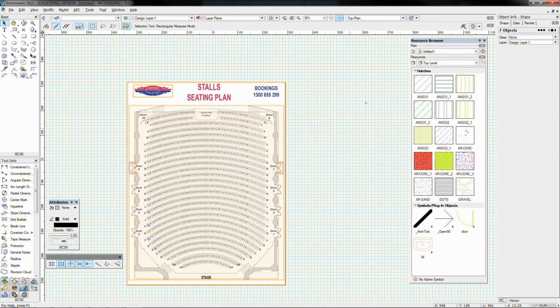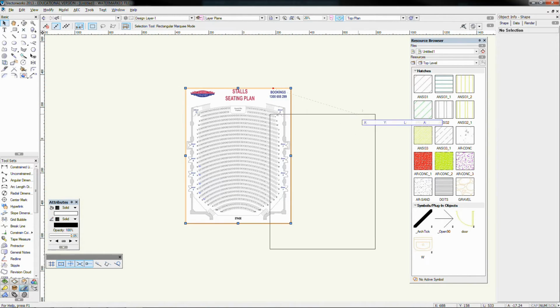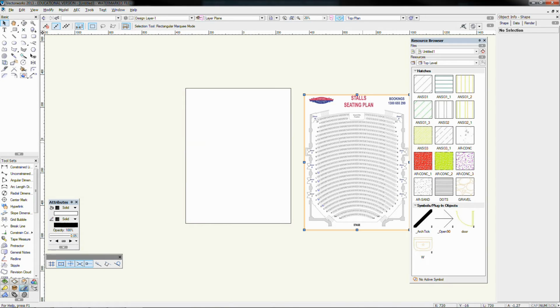And it'll probably spit out a couple of objects. There we go, 7 objects up in the top right-hand corner. Now at a guess, the smart cookie, whoever's drawn this, has broken it up into some walls, probably some seats, and maybe a few doors and some background images. So the first thing you'll be left with, if I just drag these components out individually, is the original PDF. It sits on top, you can see it's here as a bitmap image.